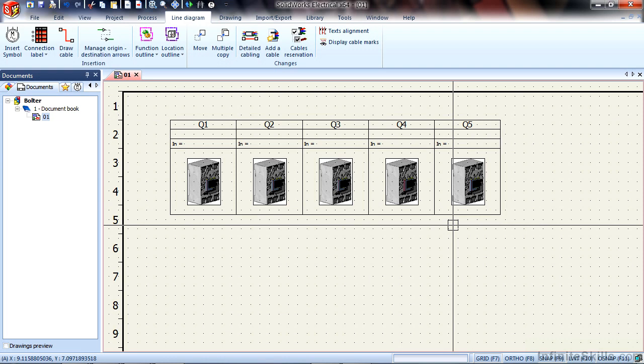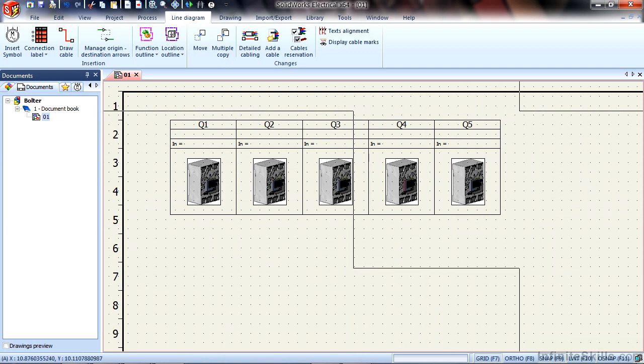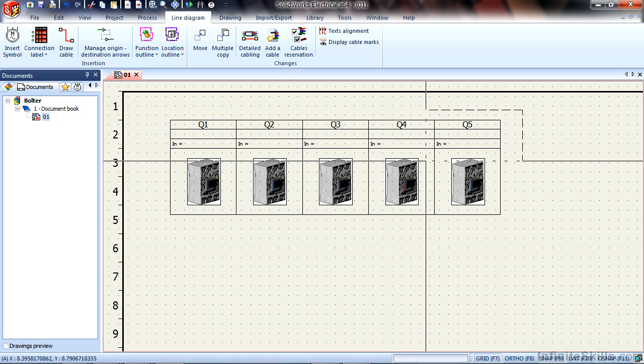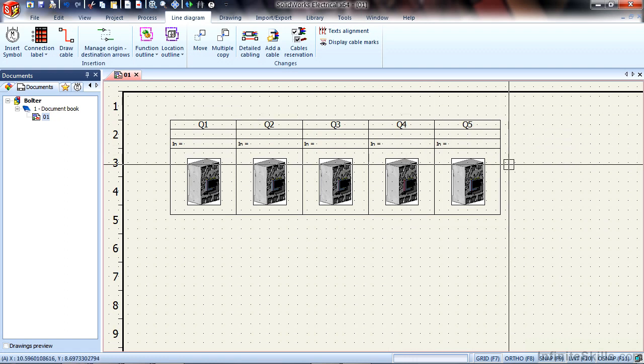Other ways of selecting objects include window selection. I can draw a window from the left to the right and select any object completely in that window. We can also perform a crossing window operation, which lets you do a window selection, but just touching the objects will select both objects inside of that window. If I did that the same way with the normal window from left to right, I wouldn't get that ability.